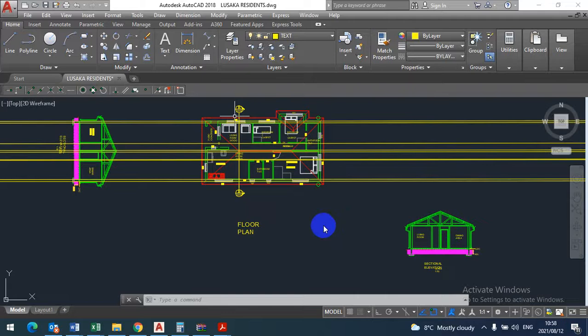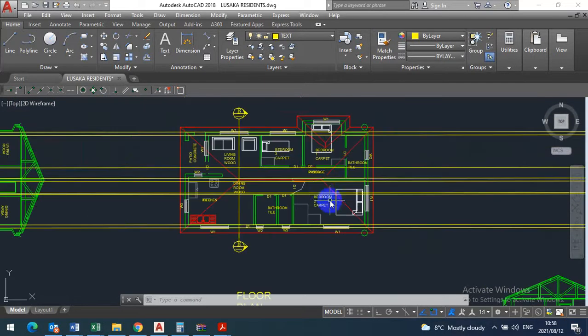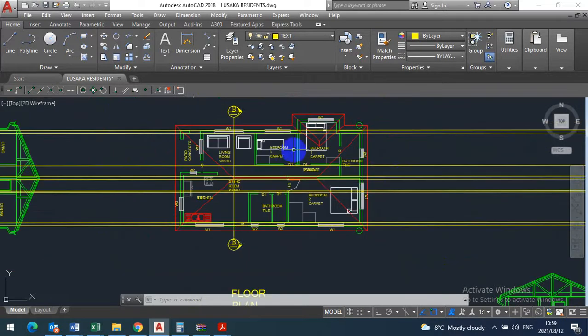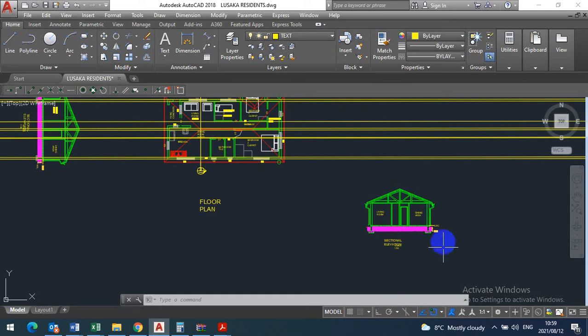We've done the floor plan. We've done the sectioning. This sectioning, I'm taking an example that was drawn by one of the students. This was the floor plan and that was the design, okay? These yellow lines that you see here are the lines that are supposed to be drawn for you to get this sectioning. This sectioning is the same as that sectioning, but why I'm keeping this sectioning here is to use it to get my elevations.